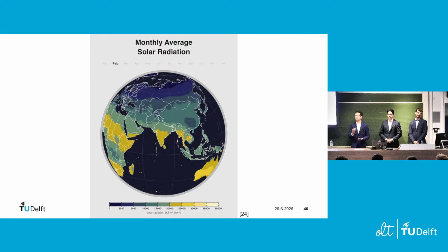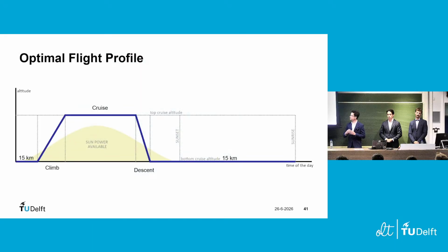For this, and in order to ensure that our aircraft comes as close as possible to full global coverage, we needed to design an operational profile that is as energy efficient as possible. And that operational profile looks something like this. During the day, the aircraft will cruise at its assigned altitude, collect all of the scientific measurements, and operate as normal.